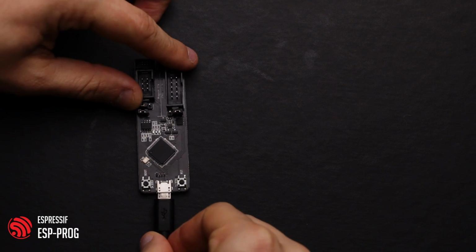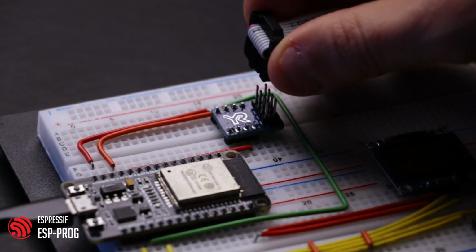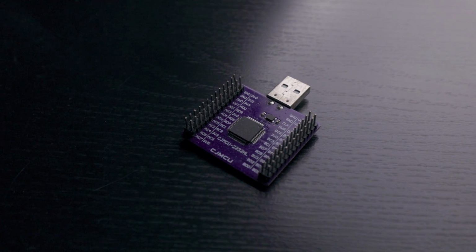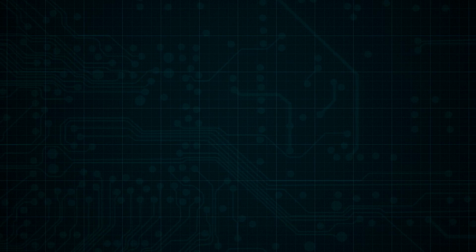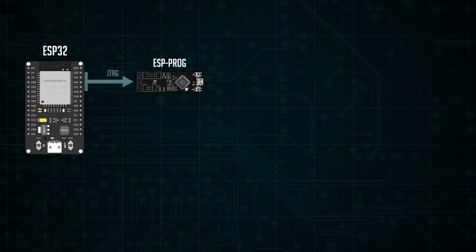Alright, let's set up our debugger. Today I'm going to show the connections for the ESP-PROG, since it's easy to buy one and it's the official debugger from Espressif. It doesn't matter which device you use in the end, as long as it supports JTAG, the pin connection for the interface should be the same. The connection with our PC looks like this. The ESP32 is connected to the JTAG debugger through the I/O pins.